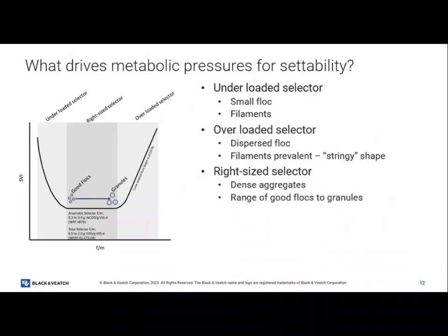But if I'm at 0.2, I can only go half that. So now my granule has to be half that, because if the food can't go in, the middle's not getting food. What happens to something that doesn't get food? It dies. The middle of your granule is dead and falls apart. So your granules are self-regulating to a degree. They fall apart because they can't grow any bigger, because the middle will run out of food.